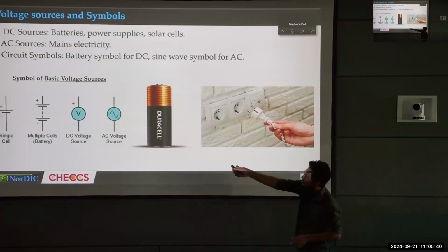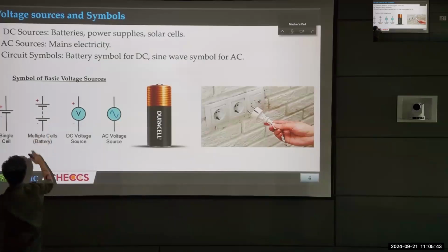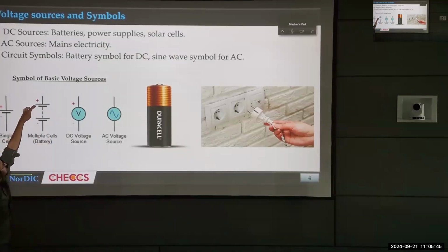So the second figure is basically the same assembly. We are connecting positive terminal to negative. This is the positive terminal of the battery, and this is the negative terminal of that battery. So let's say we connect another battery here, the positive terminal here and the negative terminal here. We connect it subsequently. Why do we do that? We actually want to create a bigger voltage difference or bigger potential difference. So for example, this is a 3-volt battery, let's say. What this does is create a voltage difference of 3 volts between this node and this node. If I connect another 3 volts here, what will it do?